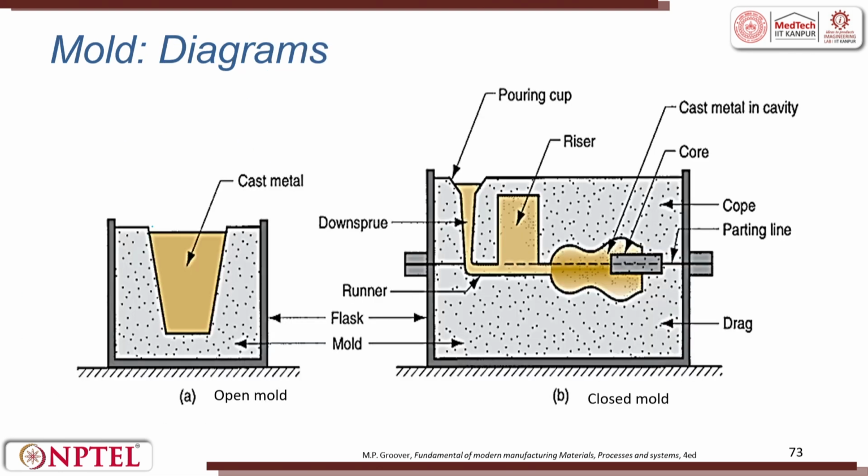This is the open mold. So, you just pour it. For example, if you have a liquid metal and you want to make ingots, then we just pour and try to make it like ingots, right. For example, think of sugarcane jaggery getting formed. The sugarcane juice is heated, the viscosity is changed, it is poured into a die and then they take the jaggery block out, right. Today you get a small injected jaggery also. Those things are called closed die. So, this is open and this is only for an ingot. Most of the time this will never be used for the final output.